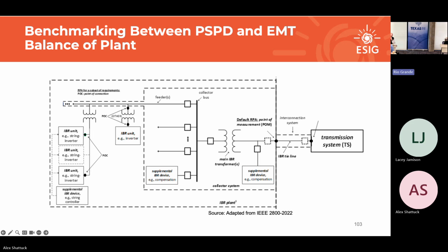So what I usually do is I'll start from an inverter and go up. We talked about the single machine infinite bus. I kind of scooch that out and test each little section at a time, right? Or you could build the whole thing and solve it in both softwares and check. And the main places you're going to see differences that you want to check, really simply, and first, is just to make sure the inverters are giving out the same amount of power and reactive power. If those are different, something's wrong.